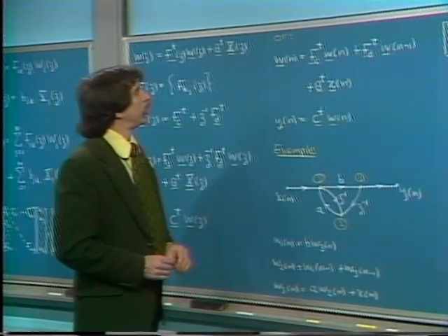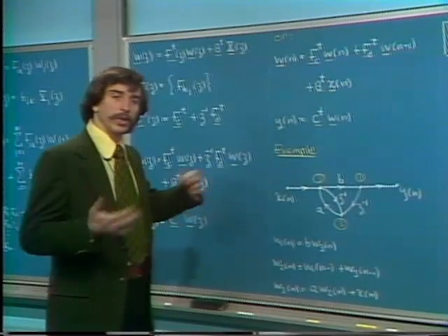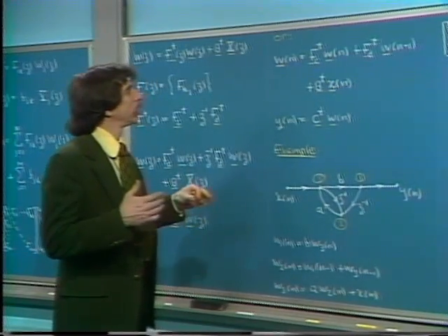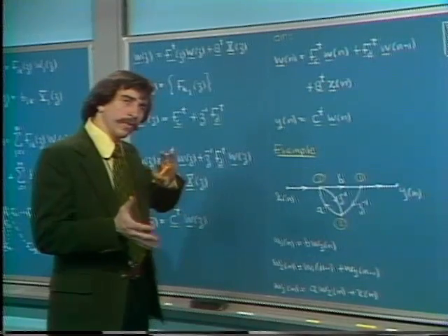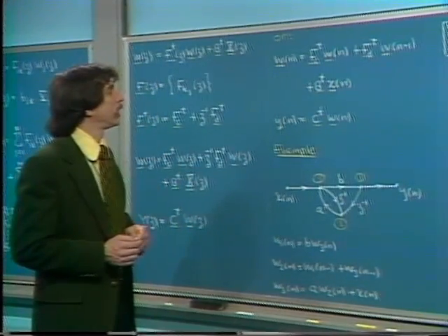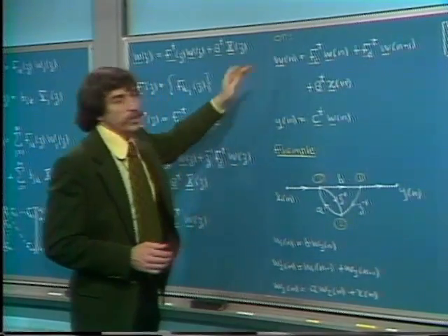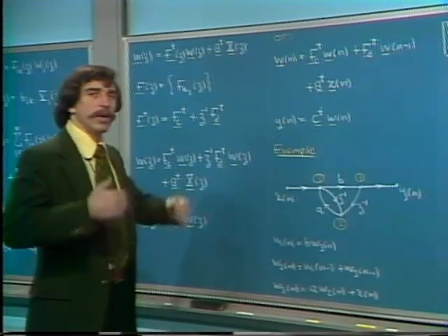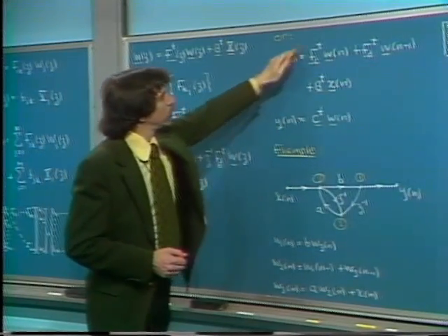And the discussion in the next several lectures will in fact involve what the various options are in terms of what various forms we can use or are commonly used in representing this large nth-order equation. But what we see is that the signal flow graph, in essence, breaks down the nth-order equation into a set of first-order difference equations.